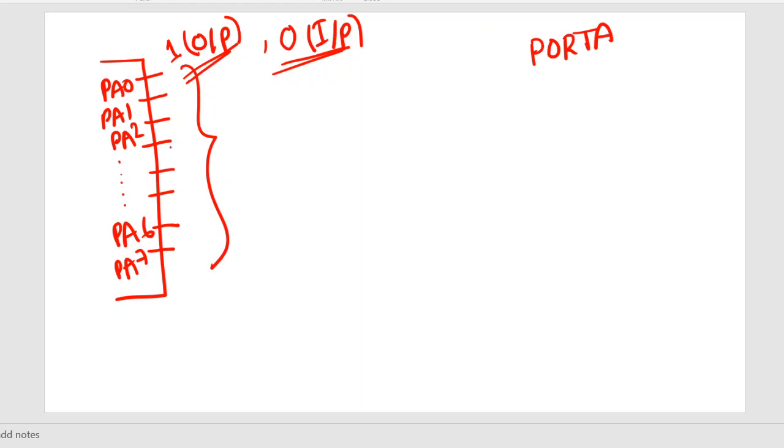So now if I want that, I will declare all the pins of port A as output pins. Then I will send 1 to all of these pins in the data direction register. In the data direction register, I will write a binary code, so I have to start it using 0B. Then there will be 8 slots for the 8 pins. The rightmost slot is called the LSB, and the leftmost slot is called the MSB, or most significant bit.